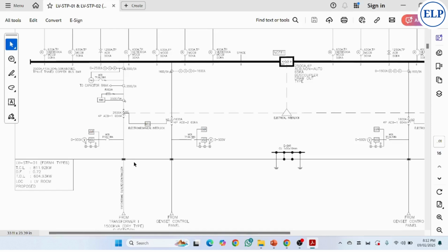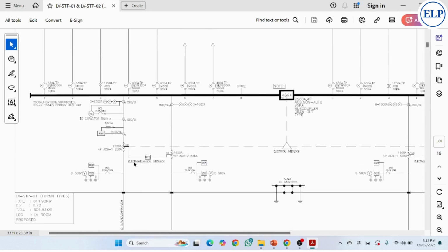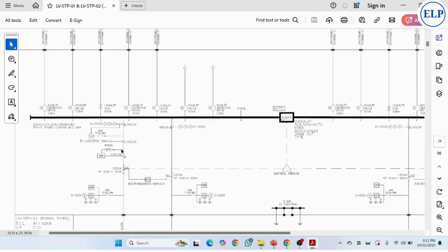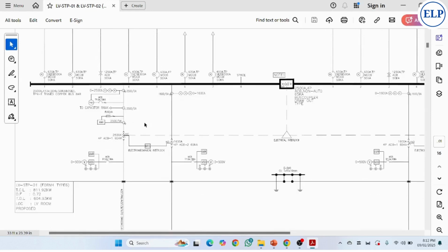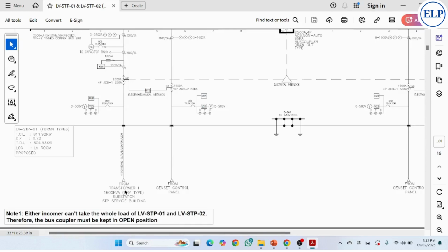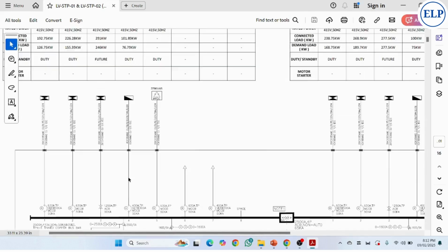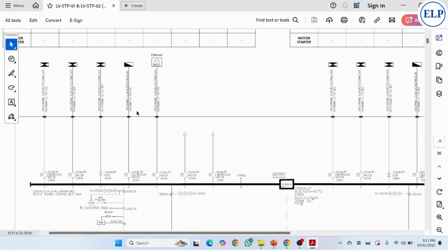The thing to keep in mind is that in ETAP, and in any other power system analysis software, the license depends upon the number of buses. Here we have components connected one to one, and the same type of connectivity we are going to build in ETAP, from the beginning connection to the end of the source connections. In the same way, breakers, cables, ended with the loads, capacitor banks and all.